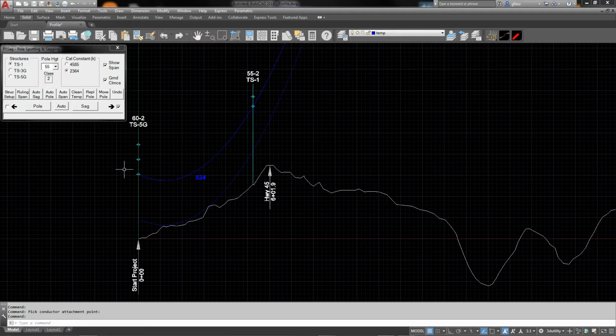Now, to greatly simplify this, I've combined these two commands into the auto design command, and with this we can move along rather swiftly. So we will use the auto design command as much as possible. Clicking this, it remembers the low point of the last conductor or the last pole that was set in place, and it will remember that unless you do an undo or delete, and then it will prompt you for that point. So we will just keep on with our auto.